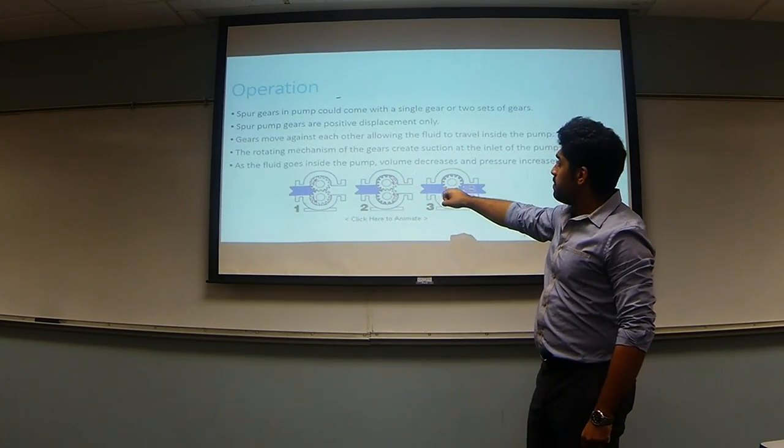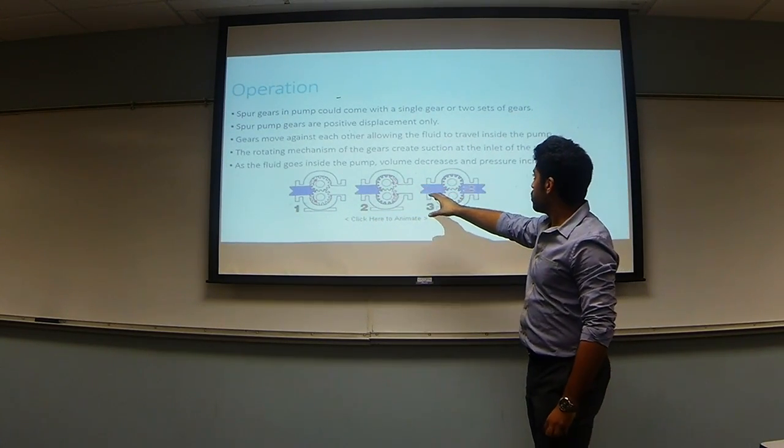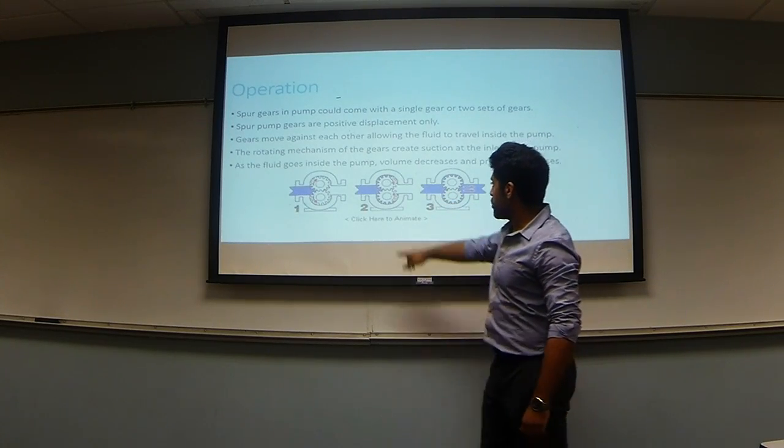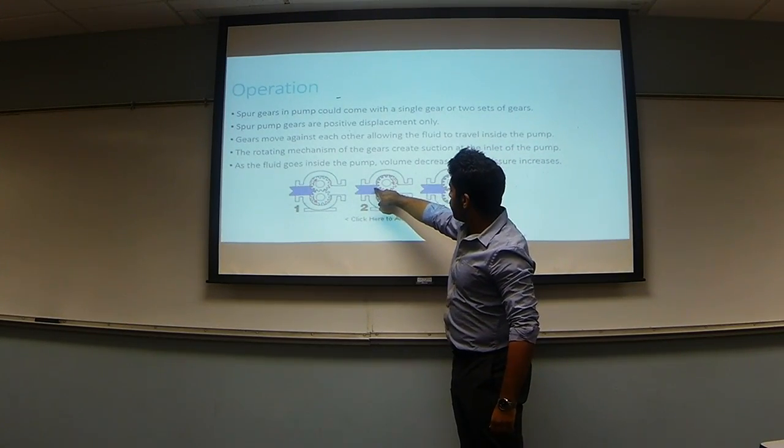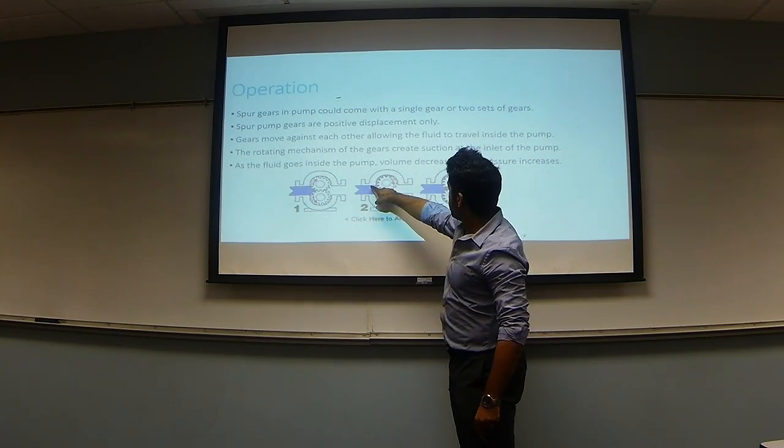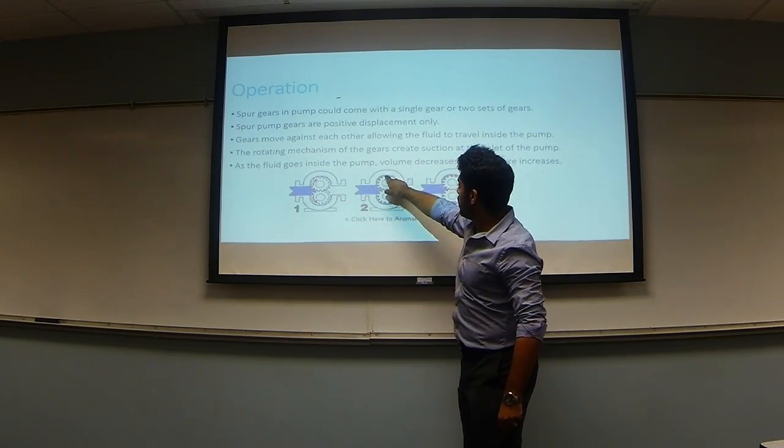The rotating mechanism of the gears creates suction at the inlet of the pump. As you can see in this figure, as the flow goes in, the liquid goes between the gear and the walls of the pump.